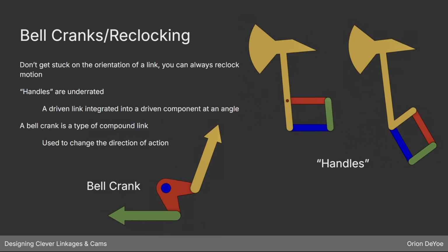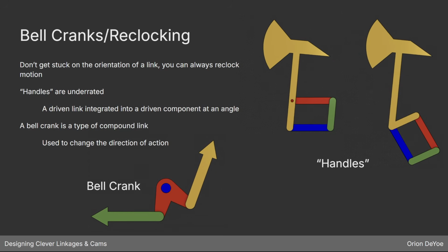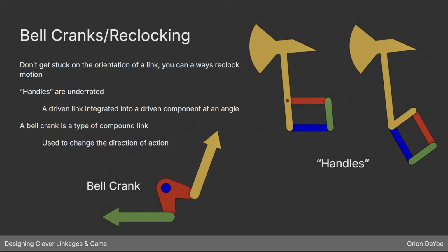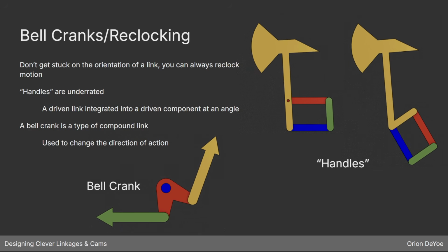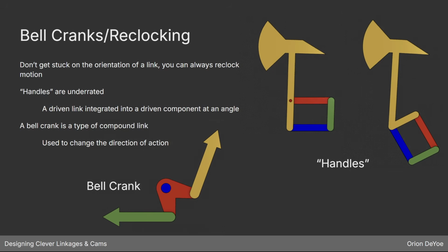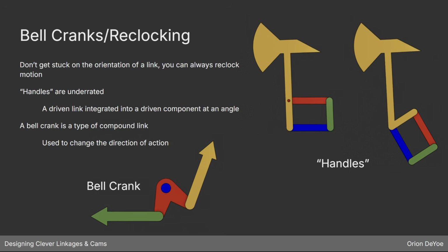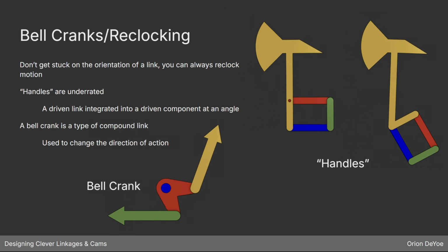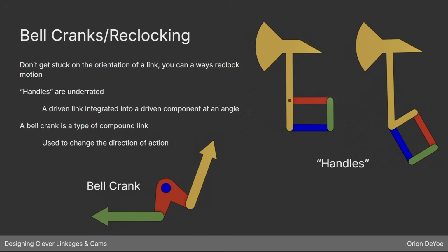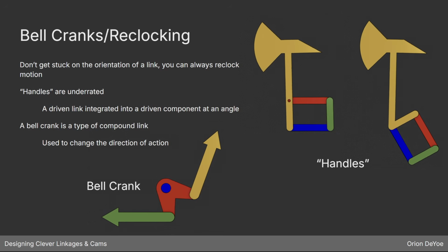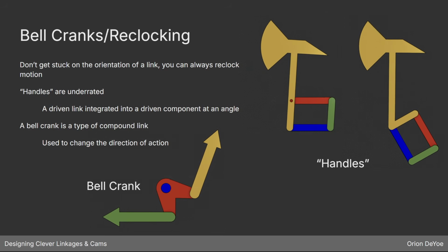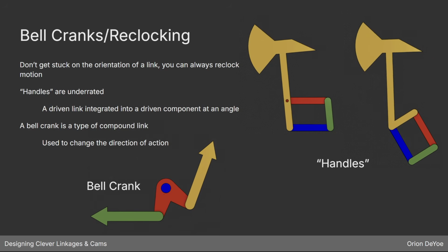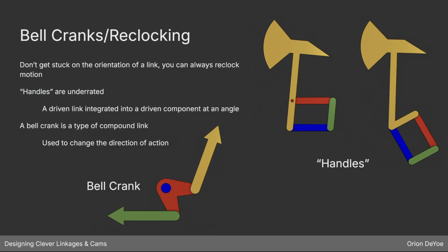Talking about a little bit more of an advanced concept here. But it's really important to believe what's on this slide, because this is one of the things I see trip up new designers a lot. Do not get stuck on the orientation of your linkage, right? Linkages don't always have to be perfectly horizontal relative to whatever you're driving, right?